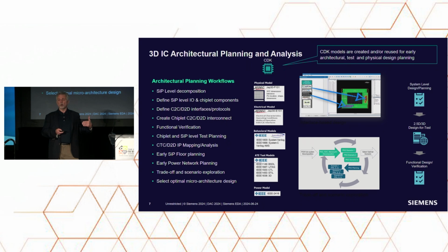But then you need to start looking at some of the technology implications. What ASIC technologies are you going to use? Or maybe not even ASIC or silicon, it may be non-silicon type technologies. So that's where you need to start collaborating with the physical designers and the package designers to decide what those technologies are. So there's some collaboration that's required to come up with the particular scenario that makes most sense for your system, for the specific needs of your system, to pick the right technologies and the right microarchitecture. That really needs to get done up front, because once you get into the implementation, if you're implementing the wrong or non-optimal microarchitecture, by definition, you're not going to have an optimal design.